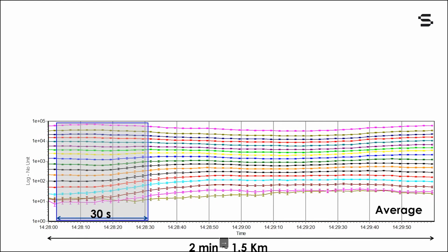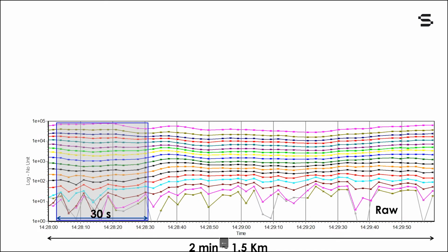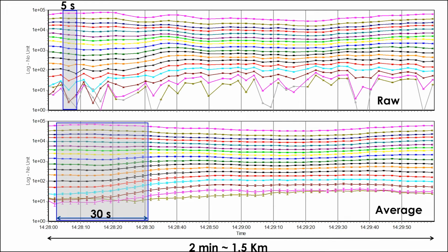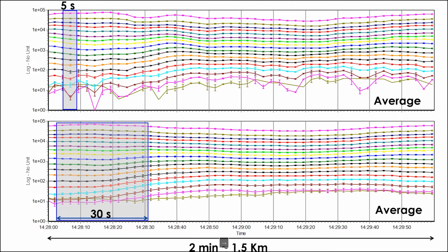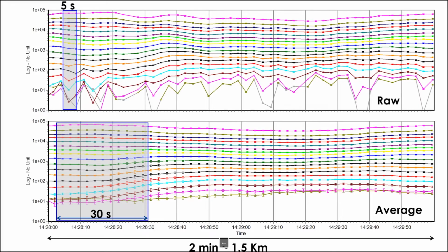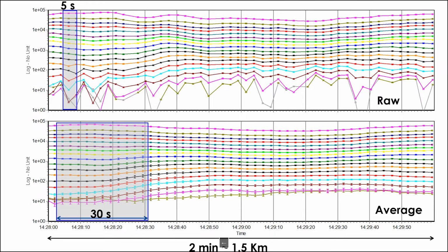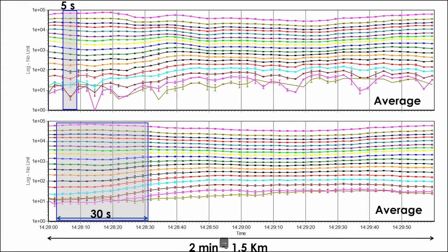So if you look at the purple one, the first time gates at the top, you actually remove a natural change in the data over the distance to be more simplified, and then you will remove geological information. On the other hand, if you take a very narrow box filter, you will keep the early time information in the first part of gates, but as you can see in the really late times, you don't really help getting much more out of this data because the box is not wide enough.